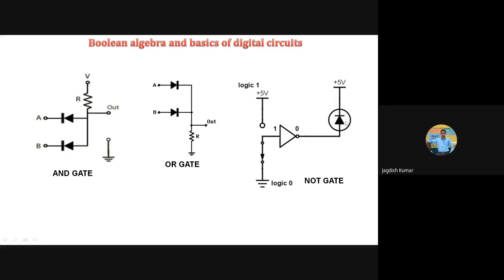So this is some sort of LED actually. Diode means light emitting diode, but when I say glow, it means it is an LED, suppose. Whenever I connect it here, the voltage here is plus 5 volt, and towards this end is also 5 volt. So what will happen? The diode won't glow. There won't be any flow of current and hence there won't be any voltage.